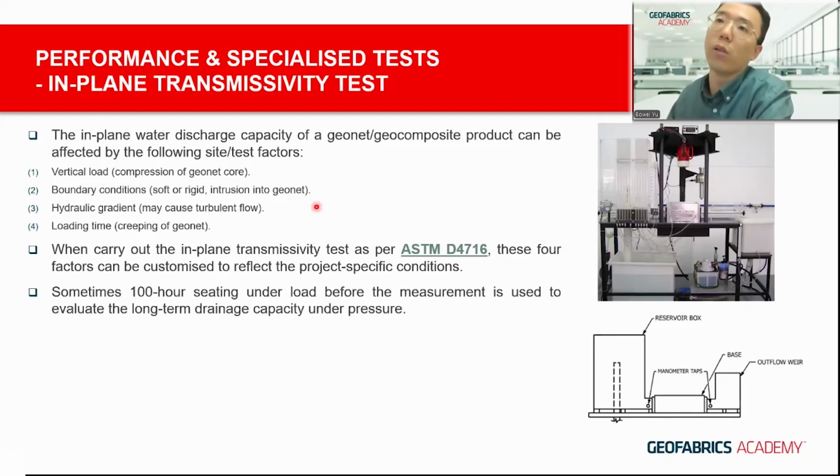And sometimes we'll also suggest to the client, instead of doing a 15-minute seating load, which we call the quick test, a 100-hour seating should be preferred because that can be more representative of the long-term drainage capacity under pressure for the geonets or the geocomposites.